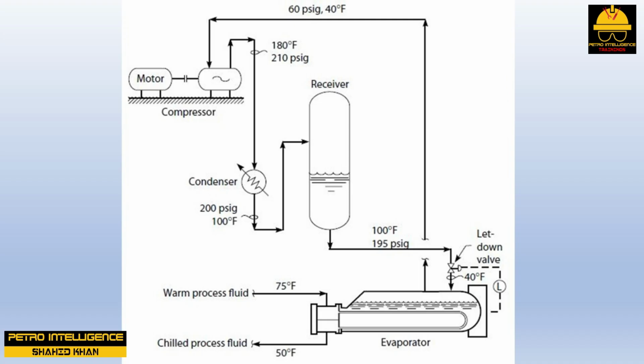Increasing the suction pressure increases the density of the refrigerant vapor flowing to the compressor. Even though the volume of gas flow is constant, the weight flow of the circulating refrigerant can be increased. Yes, we can get 6 pounds of manure in a 5-pound bag if we make the manure denser.